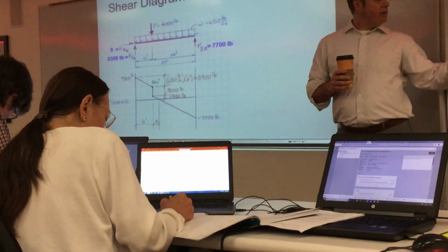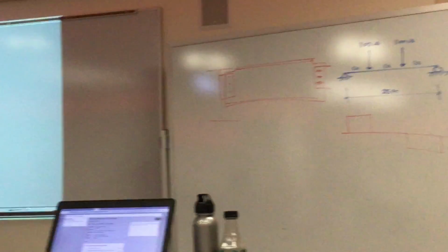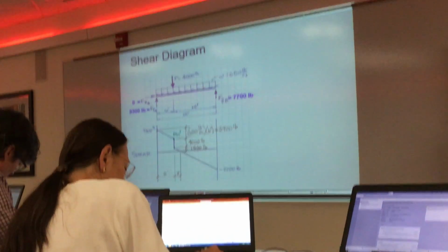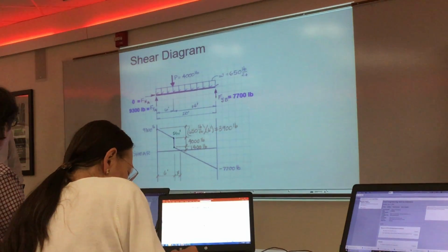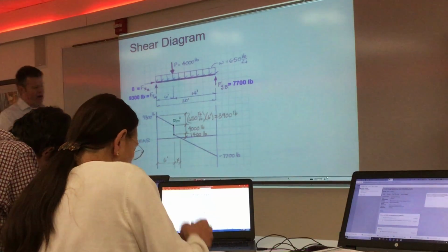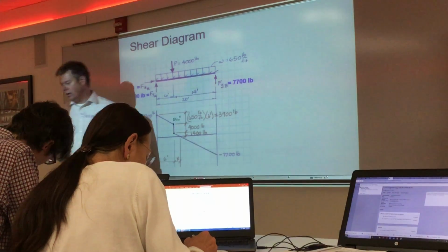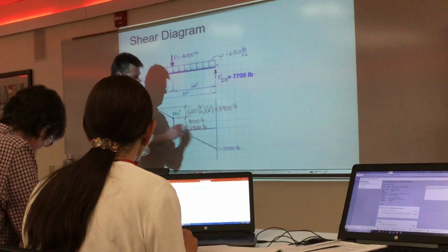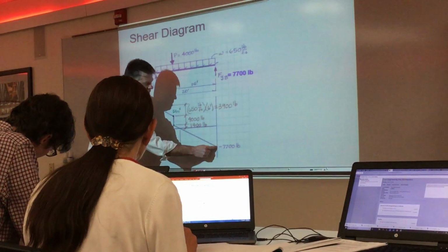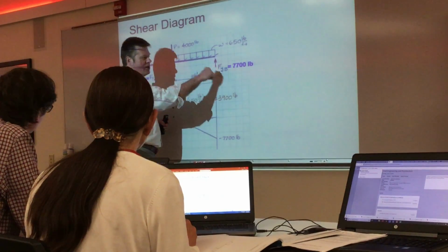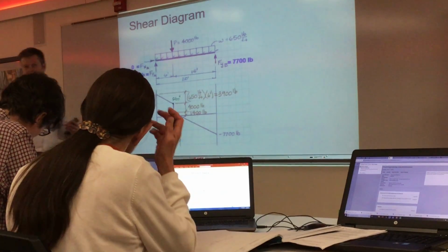That's how many bolts and welds and plate we need to handle to support it, which we don't get to in the curriculum, but that's the next step. So that negative 7,700 is what? Actually, a positive, it's the same thing on the other side. Yes, we would use the absolute value, because both of these are actually spikes up. This just happens to be across the length. So at this point, I've ended it here at the beam, and then I spike up to 0. That's the reaction that needs to hold, so that's how many bolts and welds I would need to handle on that side.